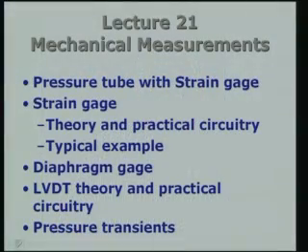So, to look at what we are going to do, we are going to look at pressure tube with strain gauge, and then we will look at the strain gauge, its theoretical and practical aspects, something about the circuitry, and then if time permits, we will take a look at diaphragm gauge and then LVDT and so on. But I think we will just have enough time to look more carefully and in great detail at the strain gauge as an instrument for measuring length and hence the pressure.